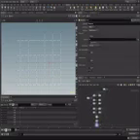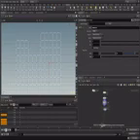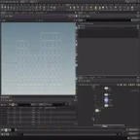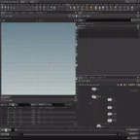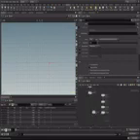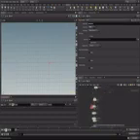And now we'll be merging this with our original mesh. Right now we've selected the endpoint, so that's nice. And here we're setting the noise. So then place down a merge and wire the two of these in there. Place down a fuse node, and we can throw it into the find shortest path node. Let's make sure that our adjusted prims are on the left. And then I want to have this grouping to be done actually after this. So the noise can be done in the beginning, and this grouping can be done over there.